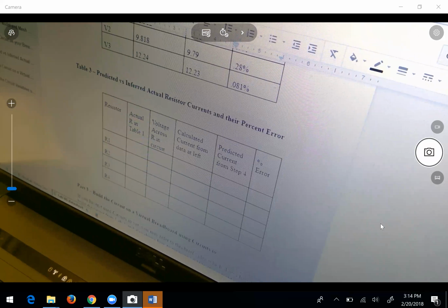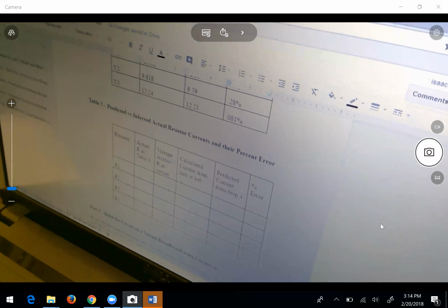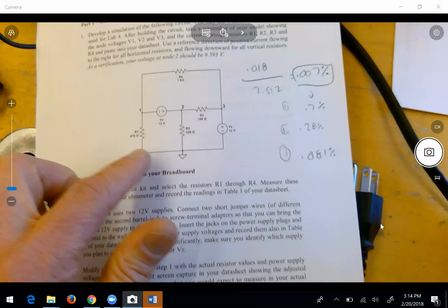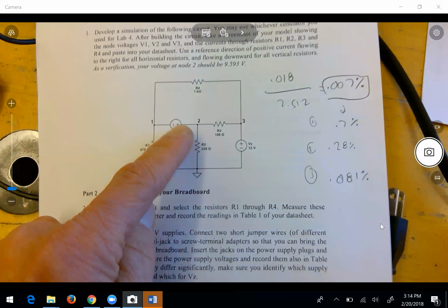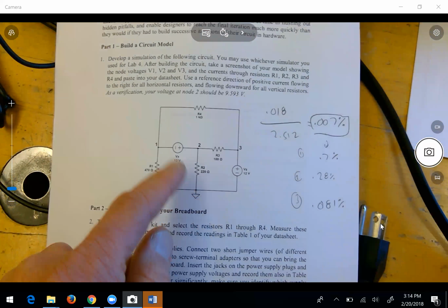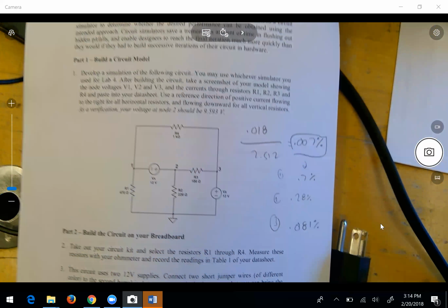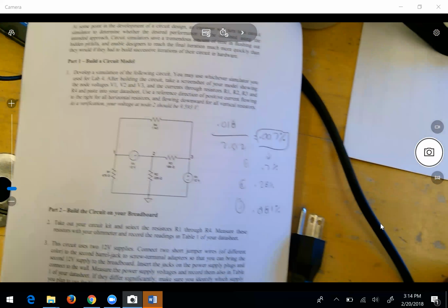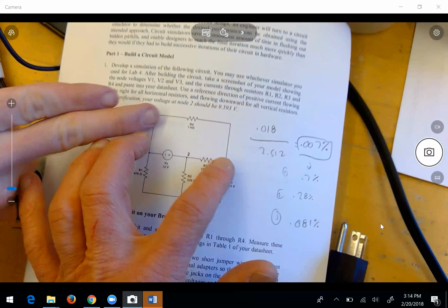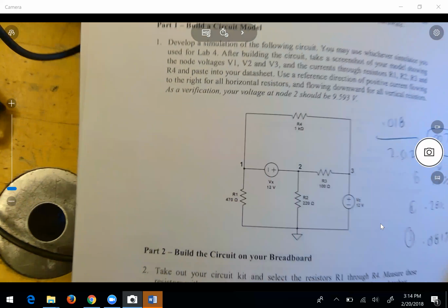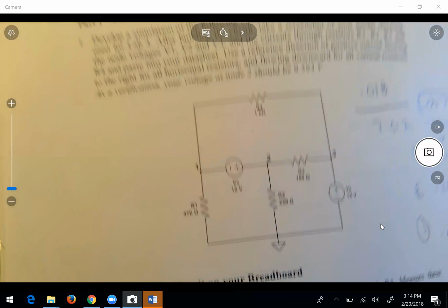It's the subtraction of the two node voltages, right? So if you want to measure the voltage across R2, it's V2 minus 0. But the voltage across R4 is V1 minus V3. It's a potential difference. Depending on the polarity of what you want, right?